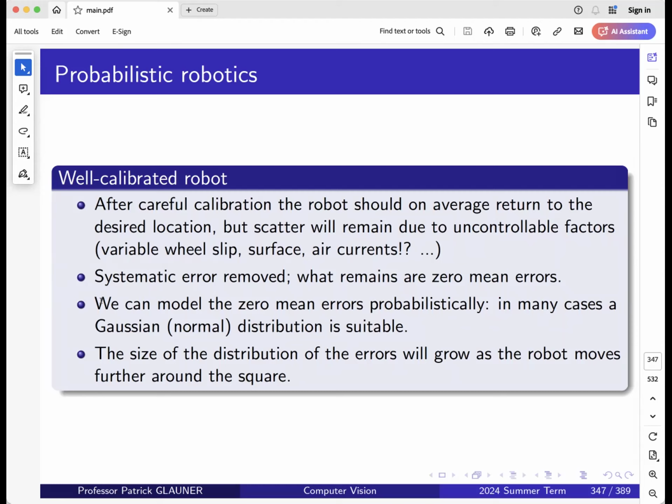If you have something like this, that the movement errors don't add up to zero, or their mean is not zero, but is somehow positive or negative, then you have a systematic error, and this could mean that your robot shifts to the left or right, for example. So that means maybe you need a better closed loop control for the motor, so that you actually have the two velocities being the same and the robot doesn't drift to the left or right.